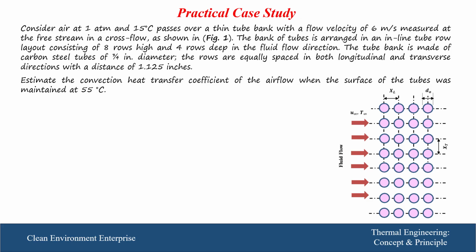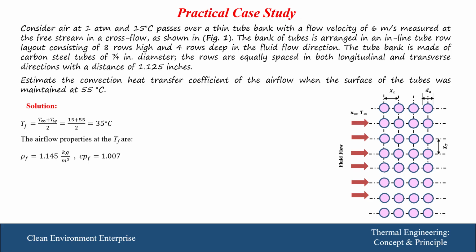We have to determine the heat transfer coefficient of the airflow where the wall temperature of these tubes is kept at 50 degrees Celsius. The solution starts by obtaining the properties of air at film temperature. Film temperature equals T infinity, which represents the bulk temperature of air, plus T0, divided by 2.